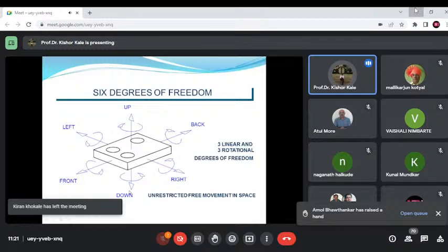So it is taken in terms of x, y, z coordinates, whatever the probe touches. If this probe touches any particular corner, it measures the x, y, z coordinate of it. So just I will let you know how this is being done. CMM measures and records x, y, z coordinates for each point measured. Which point is to be measured? All important points which you feel are important for the dimension have to be measured, creating a 3D point cloud that can be compared to a CAD drawing.